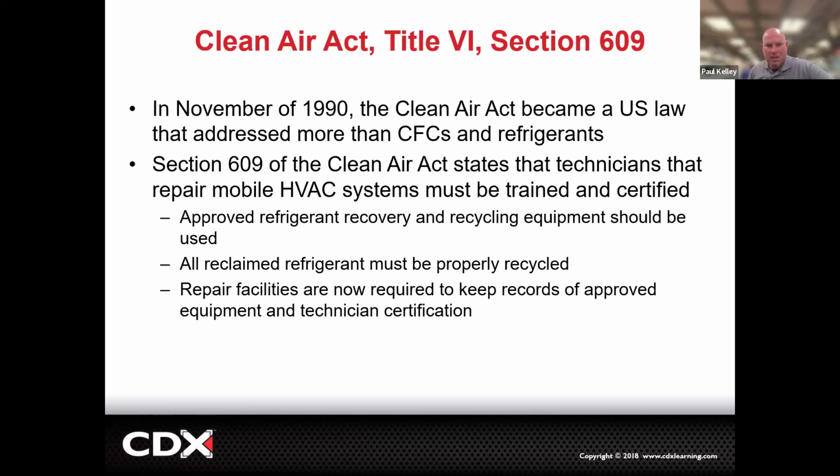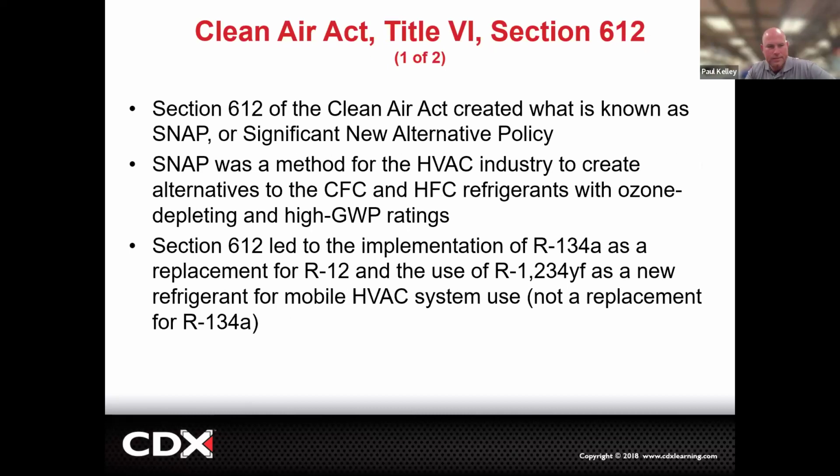That's mostly going to be handling refrigerant. Okay, so you're all going to be good. It's cheap, it's like $15. And then again, remember, all the reclaimed refrigerant has to be recycled. You can't just vent it to air, etc. We also have to keep records and use approved equipment. Some of you, when you get hired, your dealerships will have you do an onboarding package, and you might have actually got the 609 because they have to keep a record of how you're certified. So some of you might bring a 609. You don't have to pay for the 609, but if you don't have it, you're going to have to prove it. You might as well do it through ASE.